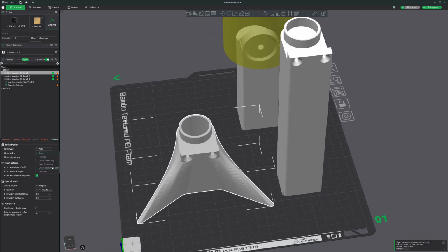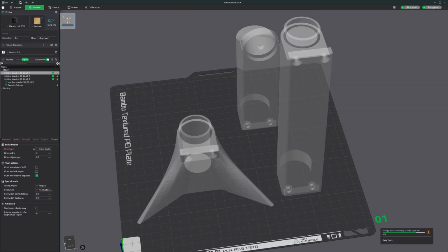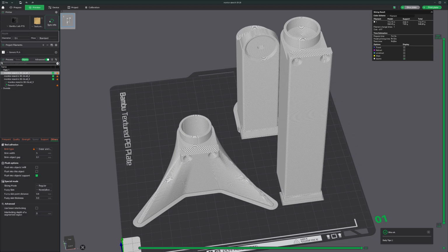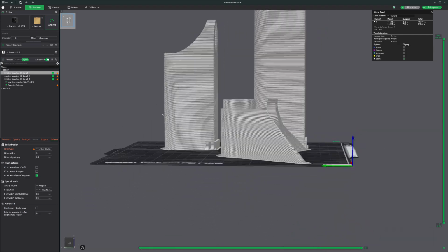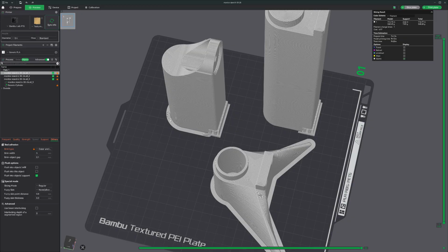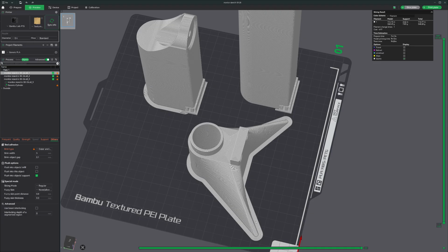There's a couple different types. I've suggested doing an outer and inner brim to a lot of you. This is a good way to go if you're not using a painted brim. I do recommend using a painted brim though over the regular inner outer brim, but the inner outer brim's just an easy setting to turn on if you're not worried about saving filament. But if you notice that there's this outer perimeter of filament that gets put down, that just helps the outside corners of your print stay adhered to the bed, and you can usually peel them off really easily.